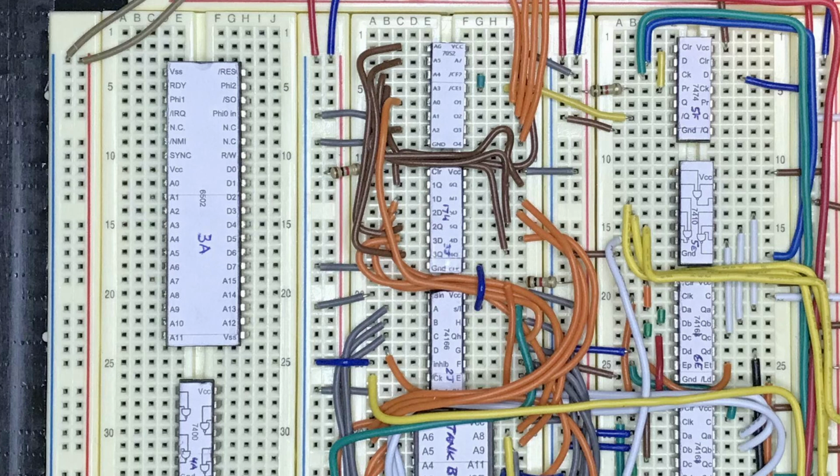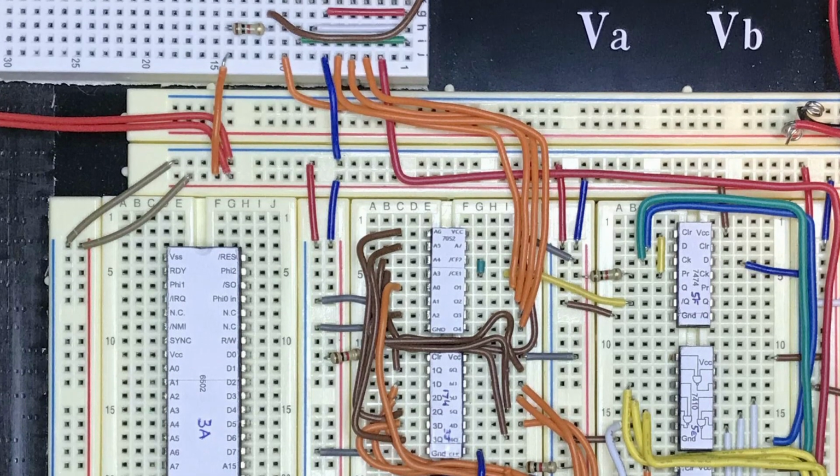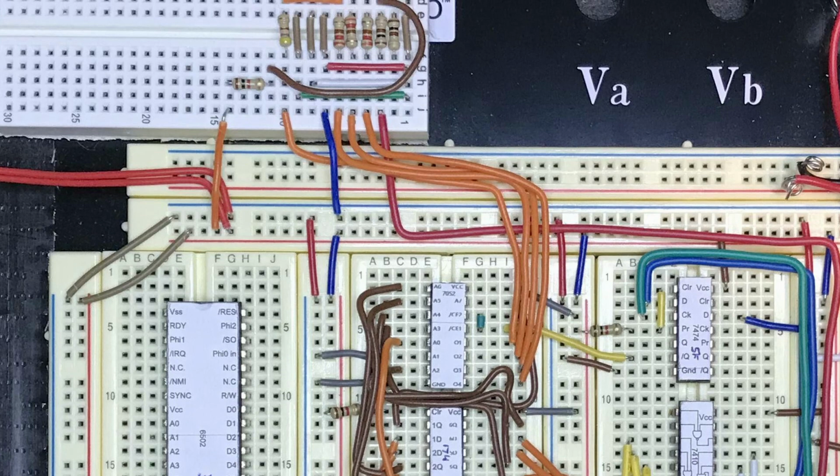Then the color PROM chip is connected to the 174 flip-flop 6 outputs and also has 2 other important inputs. The A1 input is actually from the sprite circuitry. We're not doing that part just yet, so I've just tied that to ground, giving a 0 input for this time. The A0 input is the output from the 166 shift register. This is what's going to show us a pixel or not on our tile graphics. Finally, the output of the color PROM is attached to the PVM as shown for the red, green and blue. There is an additional pin that slightly increases the brightness of the pixel, although it seems to be minimal.